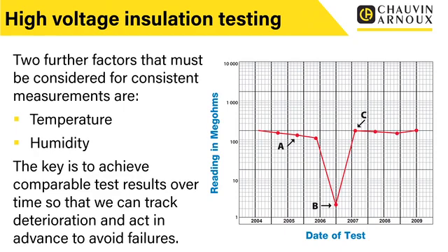Another thing that also makes a difference is humidity. We could be talking about the humidity of the air or even the humidity within the insulation. If there's moisture within the insulation, again, this can create a problem. It may not be that there's actually a problem with the insulation. It may just be that it's been in a damp environment, or it's been cleaned or washed. It could have been exposed to water. There could be all sorts of things where it may need to dry out over a period of time.